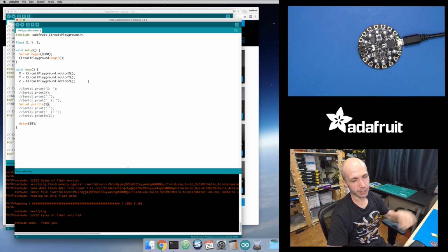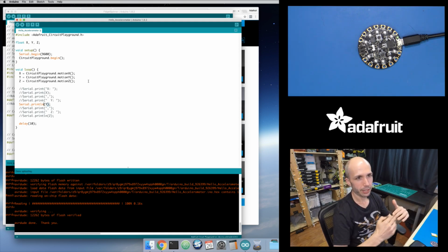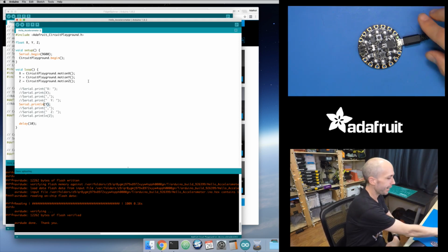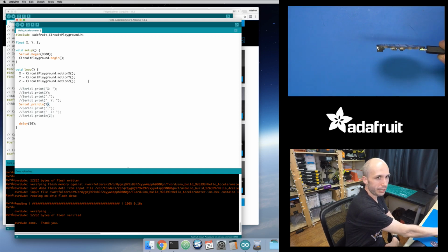So that gives me my baseline, and then I could compare my readings to that baseline to see, okay, how far are you from that average value that I've computed? And once you get beyond some threshold, then I might consider that a peak that I've detected. And that would be good, because that would protect against the case where I move the board into a new orientation, and now the new steady state is maybe above some threshold value. But that's okay, because I'm not looking at a fixed threshold. I'm looking at just the last 10 readings and their average value as my baseline steady state. So as the board changes, that baseline steady state slowly changes with it.